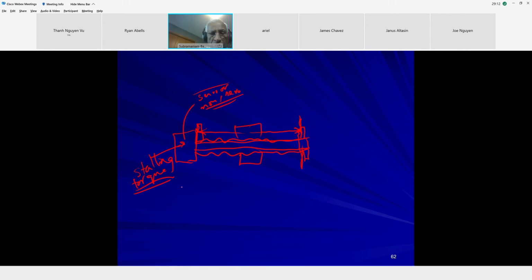The other example I would give: let's say I have an air cylinder with a piston. Now, when I apply air to this side, there are two ports. If I apply air here, this cylinder will extend to whatever it is capable of. It'll always extend to a specific end stop when I apply air. Now, if I collapse the air and apply the air here, it'll retract. Let's say this is the minimum position. It'll retract. So this is your throw, whatever the throw length is.